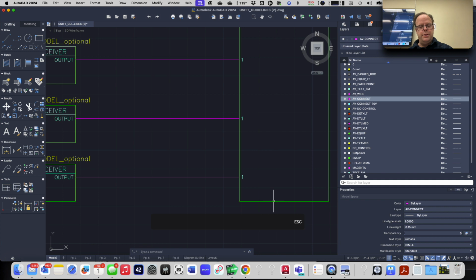Now, just as a gee whiz, what would happen if I didn't get in the habit of doing the boundary thing? So if I do extend, and I just do this, look, it'll try to snap just to that purple line. Yeah. And that would be super annoying. Yeah. And I'd be like, no, I want you to go to the green line. Couldn't you just do extend again? Yes, you could do extend again, but then, yeah. Okay, cool. But imagine you had to go through like 20 lines to get to the one you're looking for. Now you're clicking 20 times when you could have just clicked twice, right?